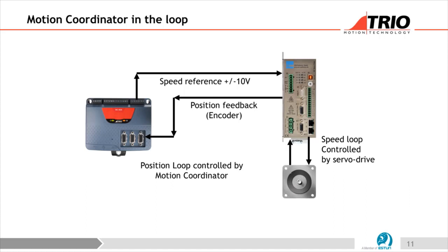But in one of our controllers, what we tend to do is the intelligent positioning bit and the motion profiling bit, and we leave it to the servo drive to do the control of the motor, if you like. So we're not really involved in controlling a stepper motor or a servo motor as such. We leave the drive to do that.